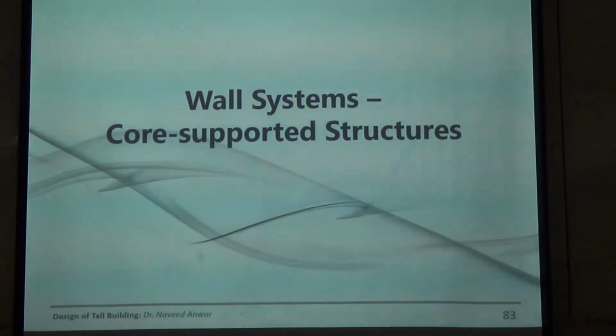So we can use this to decide whether we want two walls to work together or not, and how much, by controlling the bending moment capacity, because that can control shear capacity. But that is only possible for earthquake. For wind, we do not have that option. So in that case, we must design it based on the capacity of the link beam. So this is an important consideration in tall buildings that bothers the engineers all the time, like he was mentioning.